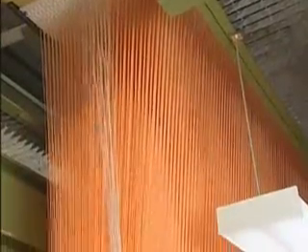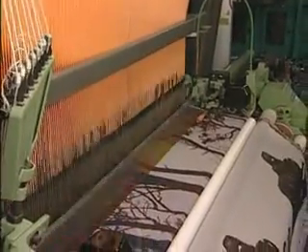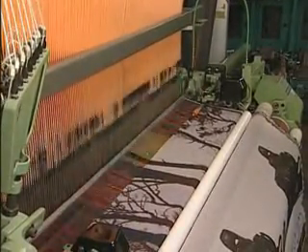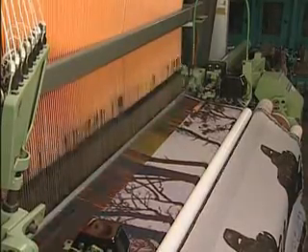Jacquard shedding exhibits control on each individual warp yarn independent of all other warp yarns. Up to 12,000 warp ends can be controlled. These systems can employ mechanical or electronic devices to actuate the warp ends. Design capability is virtually unlimited. Pattern areas can equal the width of the fabric and are almost unlimited in length. Fabrics made on jacquard looms are normally more expensive because of their complexity and slower weaving speed.